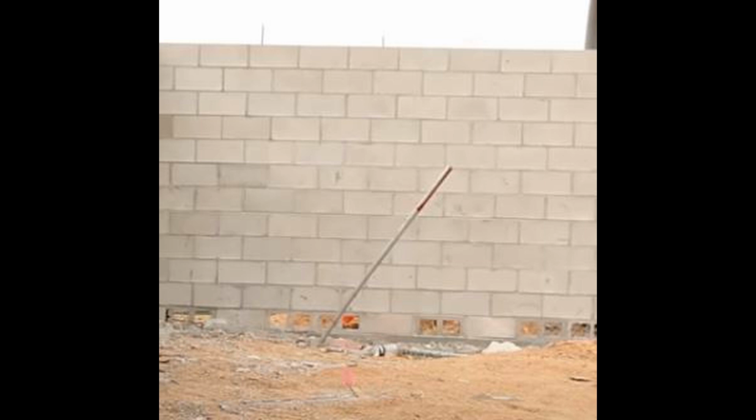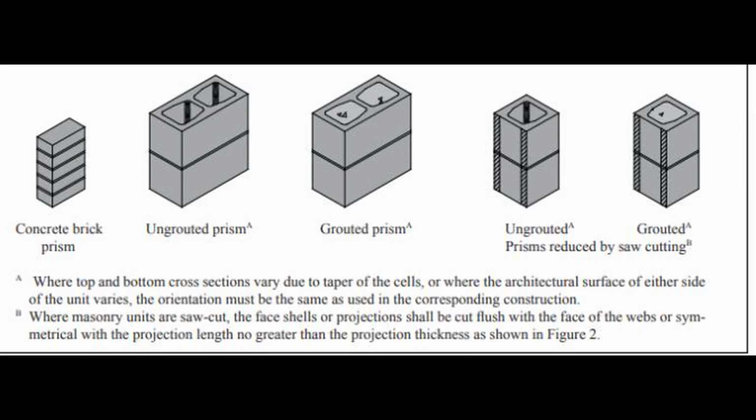Also, with the given arrangement of footing, rebar and sizing, it will take a live load of about 4 kilopascal. And it will sustain a wind load of about 45 km per hour. And for that, we need to ensure that the compressive strength of the concrete block using type N mortar is at least 15 megapascal.